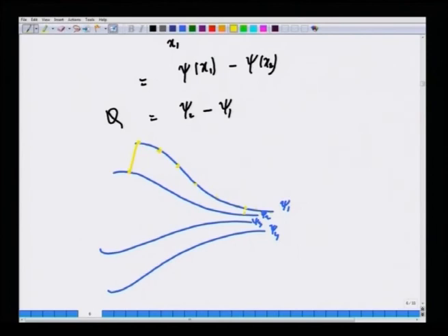That means that the velocity here will be less compared to the velocity here, because these 2 streamlines are converging. So, by having a quick look at the streamline distribution in a fluid flow, you can immediately say where the fluid velocity is going to be larger and smaller, because the difference between values of stream functions between any two streamlines is always equal to the amount of volume that is going to flow across any line drawn between these two streamlines.